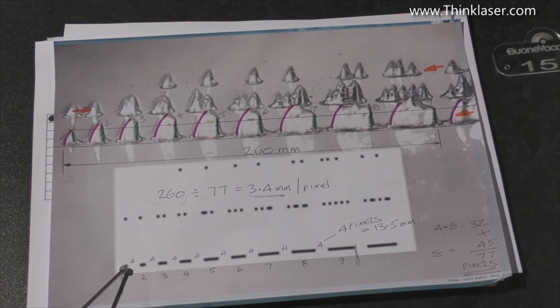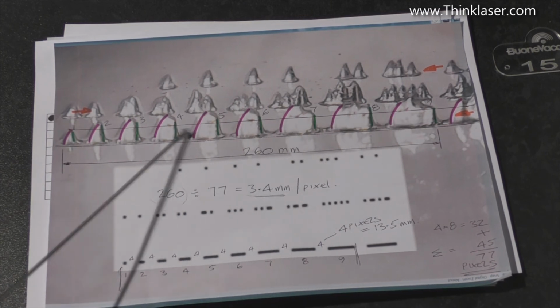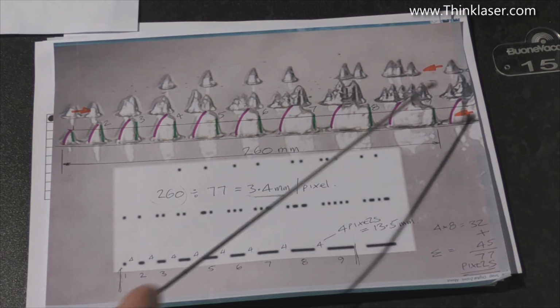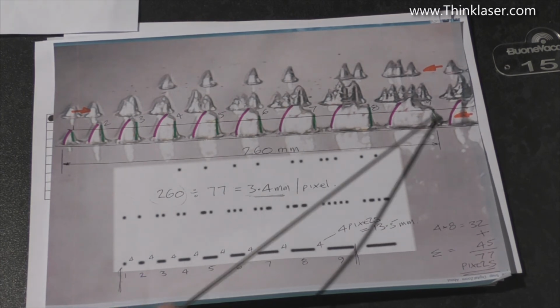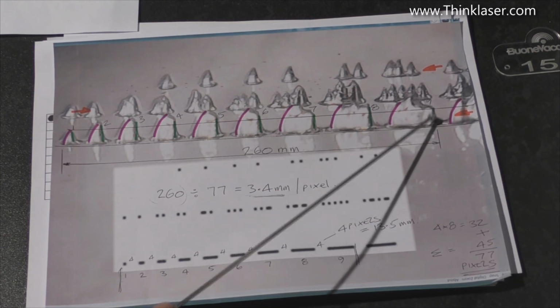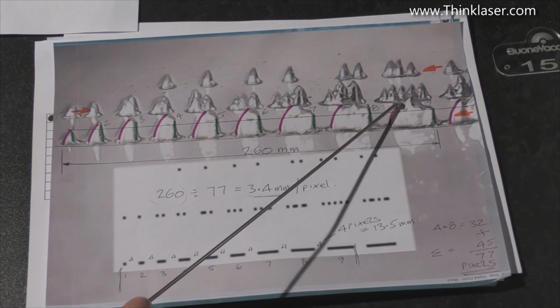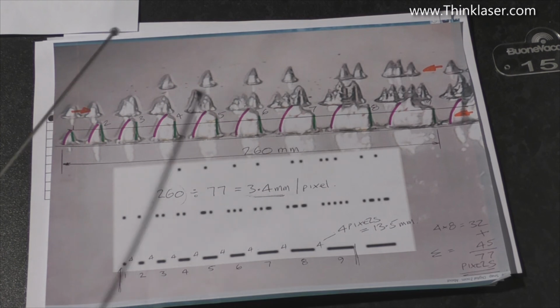So we've got 1 pixel, and then we've got a 4 pixel gap, 2 pixels, 4 pixel gap, 3 pixels and a 4 pixel gap, and we did that all the way up to 10 pixels. And so that's 1, 2, 3, 4 as it says on here. The 10th one is missing. What we find is that the rise time, the time that it took for the beam to form, that green line, is virtually nothing. This was 9 pixels wide, and we've got some very strange effect taking place here, and then once the beam switches off at about here, we've got this pink line which shows the decay of the beam, the time the power actually takes to disappear.